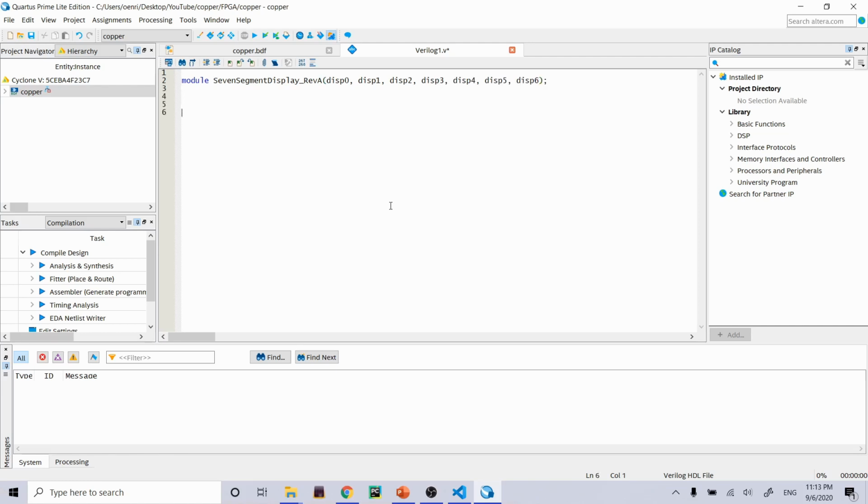Alright, and then go add the end module. Okay, so we are going to define these as 7-bit output buses. So to define 7 bits, we... always messing up my keywords. Output [6:0] display0. Okay, and one thing, notice I am neglecting the reg keyword because I do want to leave these directly as wires. We're going to see how that works right now.